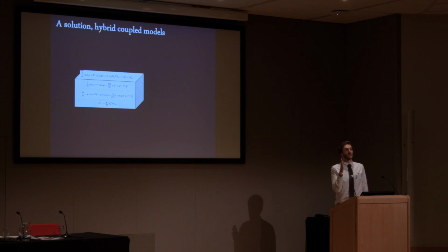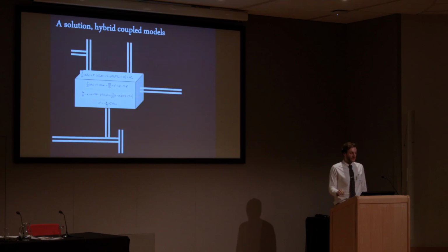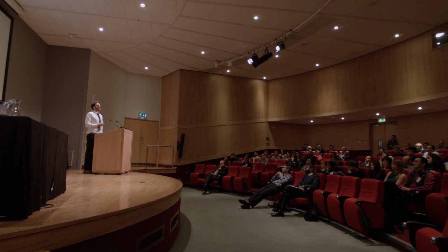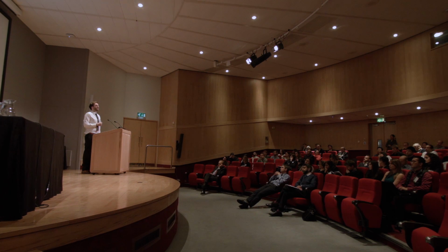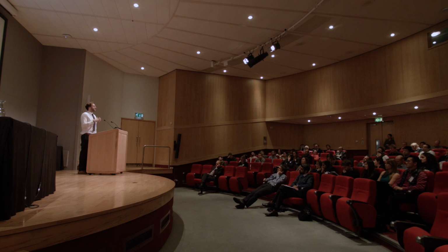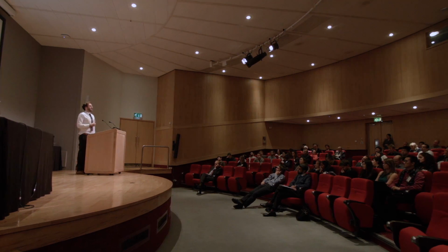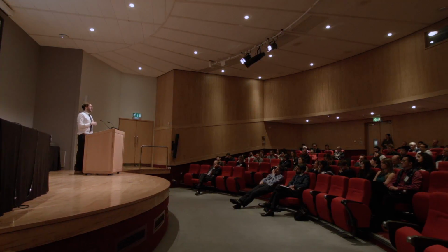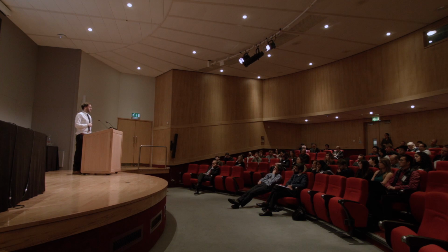So instead of curtailing our domain there, what we can do is expand our boundary conditions and include a much simpler model, for example, a one-dimensional network model, which is formed of ducts and nodes, which we can use to represent the total building system: shafts, stairs, other stories, risers, doors opening and closing.